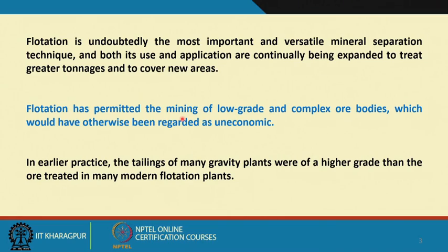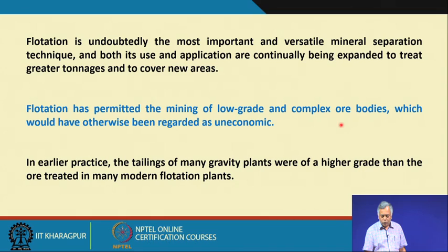Many times the grade may be good, but the way it is distributed across the matrix of a mineral, that again demands very fine grinding. So, this is what I try to say, that flotation has even permitted the mining of low grade and complex ore bodies, which would have otherwise been regarded as uneconomic, that is, would not have even mined them.